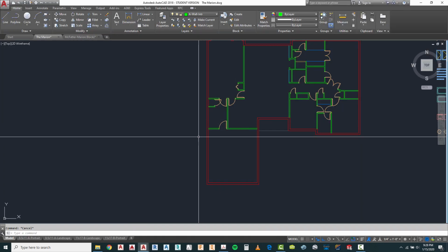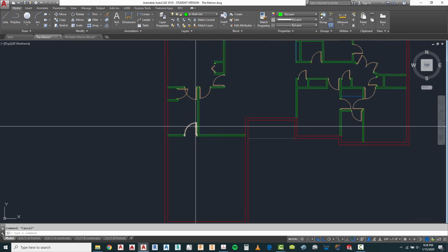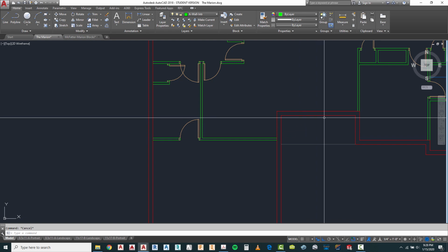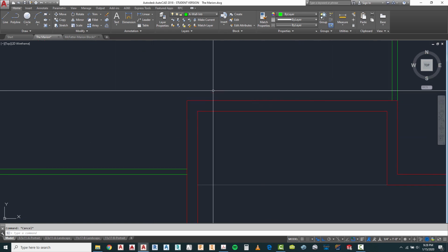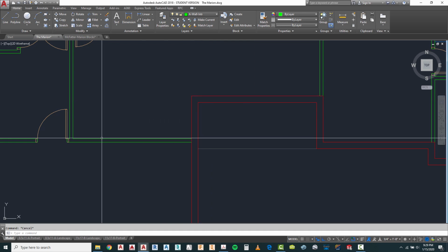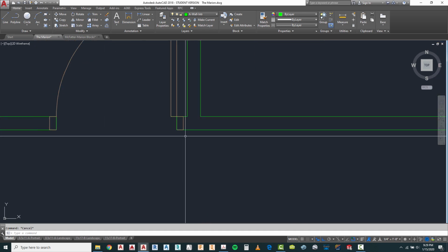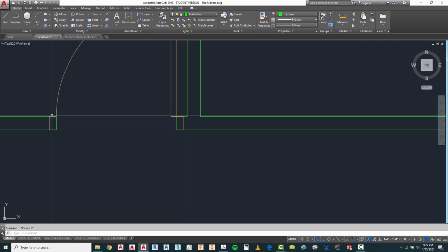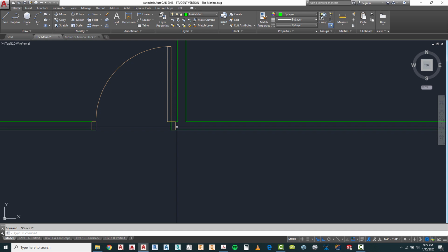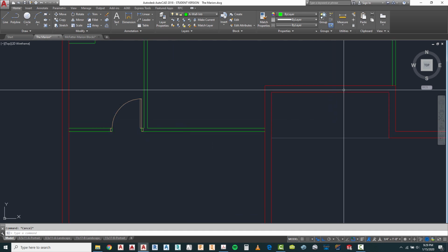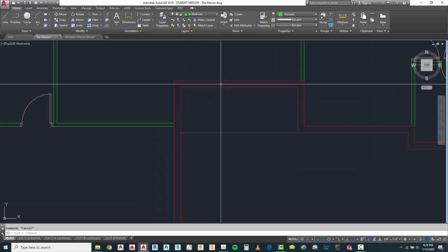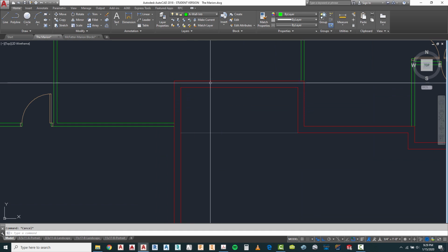So let's go ahead and select our 3/0 doors. I know this is a 3/0 door. We talked about that before. But watch what happens when we have to place that on an exterior wall. This is a masonry wall. Our jambs right here for the doors in a frame wall are actually part of the framing of the wall. In a masonry wall, it can't happen. So it cannot actually be put inside of the wall.